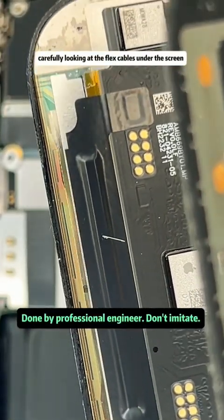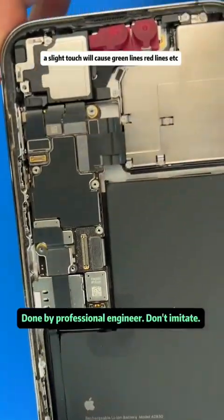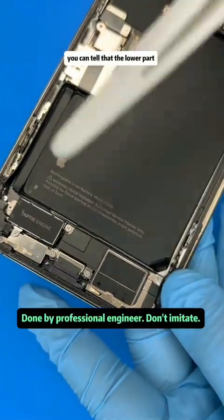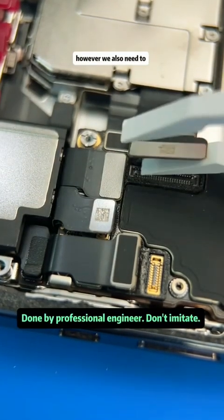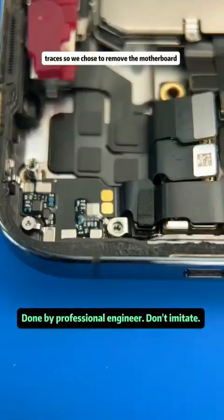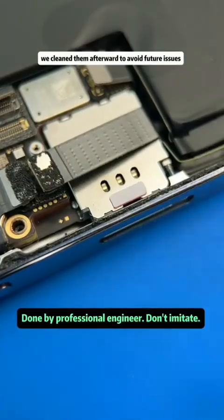Carefully looking at the flex cables under the screen, they are glass. If you're not careful, a slight touch will cause green lines, red lines, etc. From the traces of infiltration, you can tell that the lower part was infiltrated while the upper part was not. However, we also need to rule out other areas for corrosion or infiltration traces, so we chose to remove the motherboard, allowing us to see the corrosion points firsthand. We cleaned them afterward to avoid future issues.